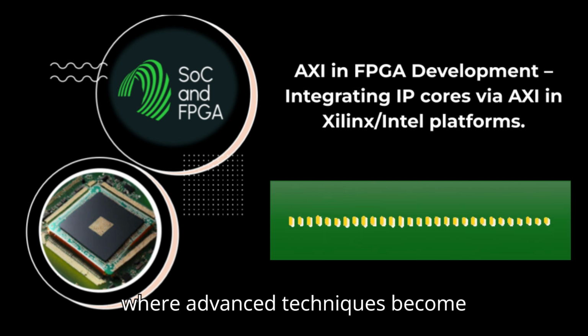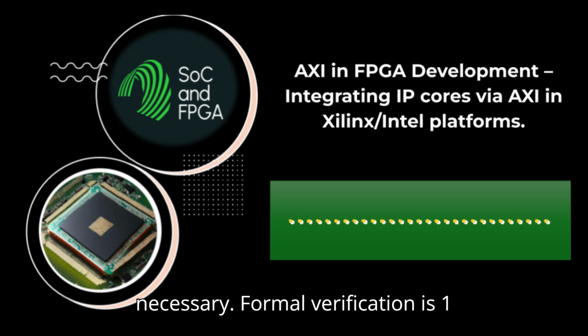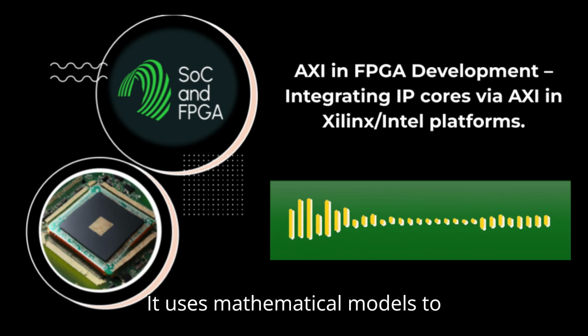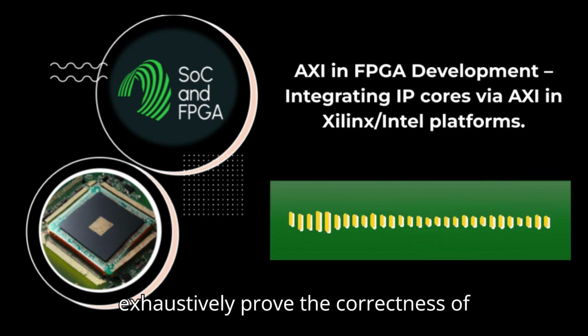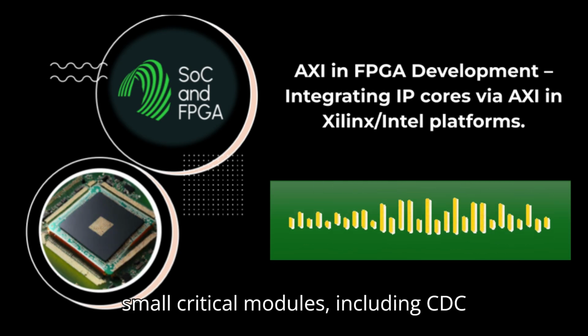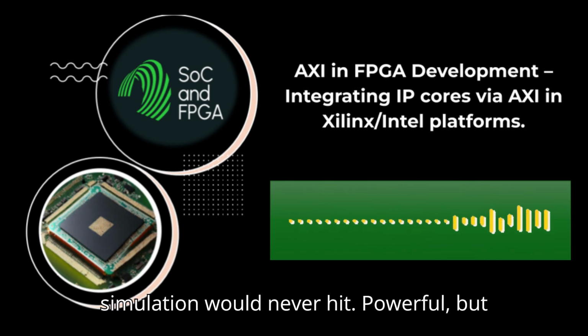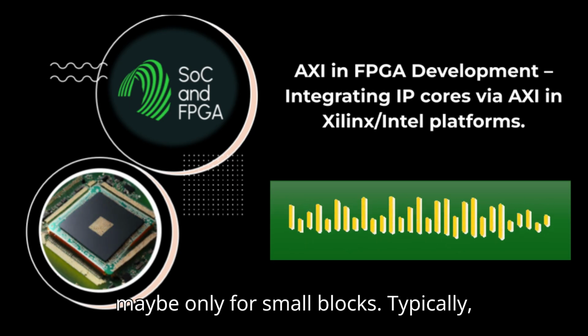Absolutely. This is where advanced techniques become necessary. Formal verification is one. Formal, like mathematical proofs. Exactly. It uses mathematical models to exhaustively prove the correctness of small critical modules, including CDC synchronizers. It can find corner cases simulation would never hit. Powerful, but maybe only for small blocks.